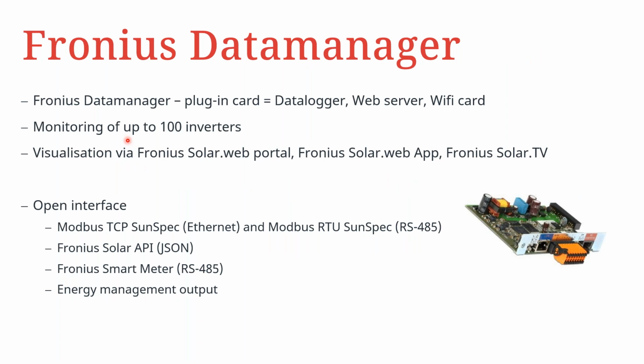For those of you who are not familiar with the data manager, the data manager is a plug-in card that looks like this, the image you can see here, and is the data logger, is also the web server, is also the Wi-Fi card. So this gives you a Wi-Fi access point when you're doing the commissioning of the Fronius inverter. Theoretically, you can connect up to 100 inverters to one data manager, but of course, depending on the setup, we always recommend to do an analysis of the kind of system that you are doing and to determine how many data managers or how many inverters can be connected to one data manager in that case.